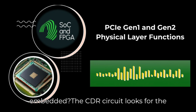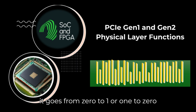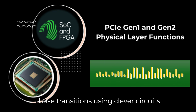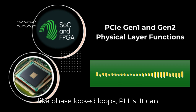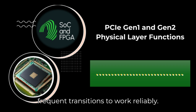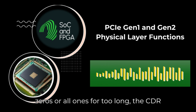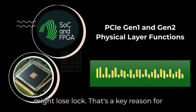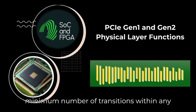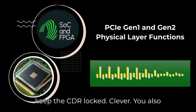How is it embedded? The CDR circuit looks for the transitions in the data, the edges where it goes from 0 to 1 or 1 to 0. By constantly tracking the timing of these transitions using clever circuits like phase-locked loops, PLLs, it can reconstruct a clock signal that's locked to the incoming data rate. So it needs frequent transitions to work reliably. Absolutely. If the data stayed flat, all zeros or all ones for too long, the CDR might lose lock. That's a key reason for using 8B10B. Encoding it guarantees a minimum number of transitions within any given stretch of data. So 8B10B helps keep the CDR locked.